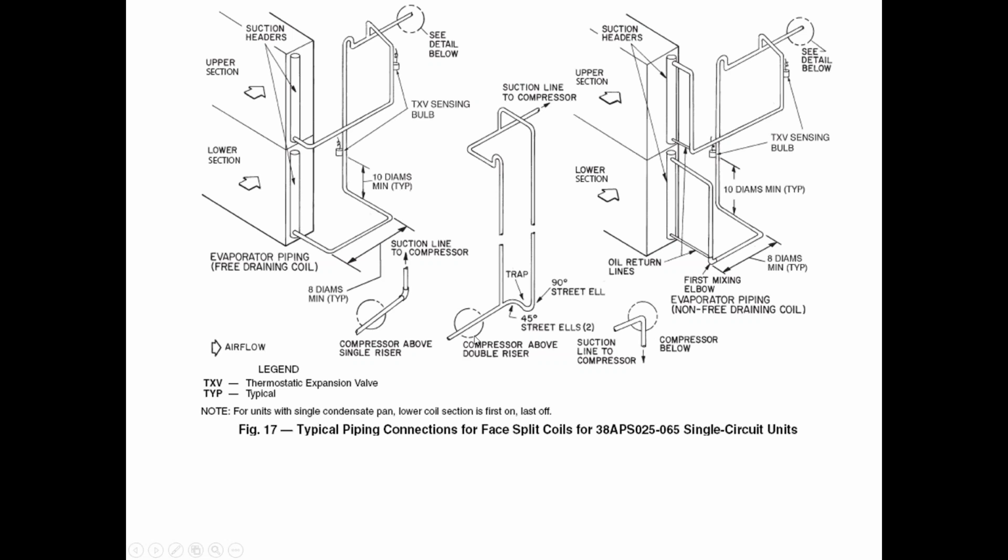We'll start getting into now some of the double suction risers and the double suction riser construction, which is right here. When we talk about double suction risers, the smaller pipe is always going to be your A pipe. This will always be the B pipe. And remember over here, your main suction run back is the C pipe. So when we look at the charts here in a little bit, you're going to see A, B, and you may see C on some of our charts.